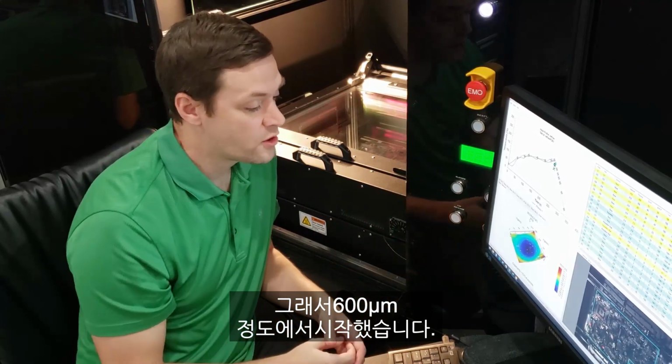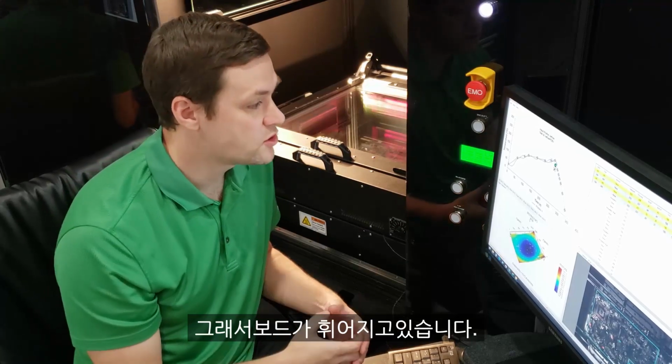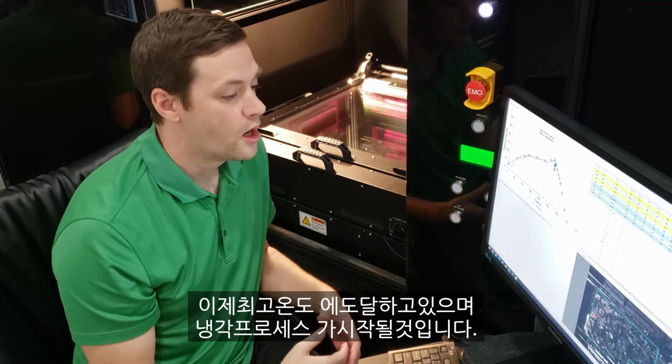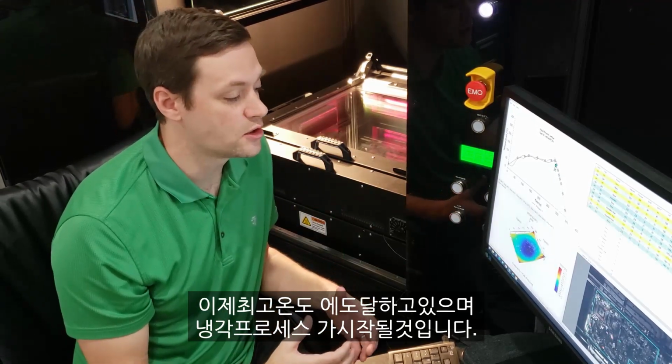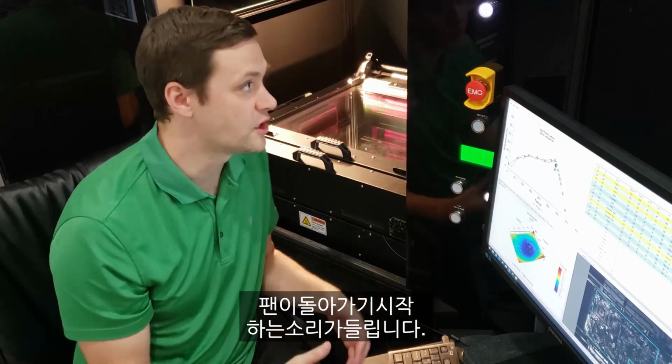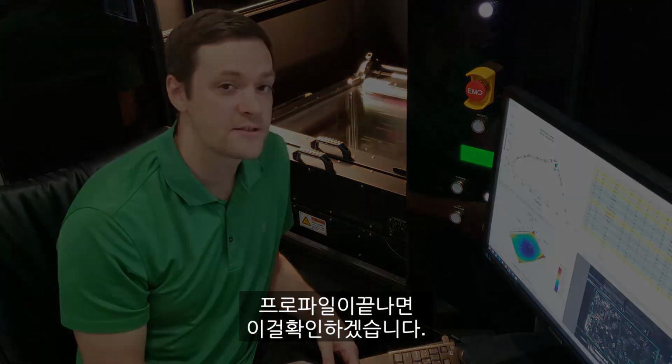So we started around 600 microns. We're now near 1600 microns in shape, so the board is warping. We're hitting peak temperature now, and our cooling process will start as that occurs. You can hear the fans start to kick on. So we'll check on this as the profile ends.